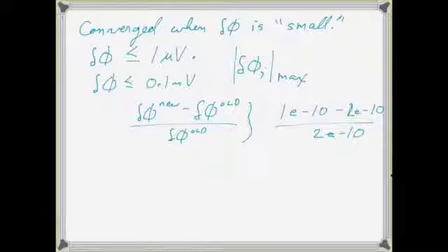You'd find some nodes that just keep going up and down and up and down. Nobody cares. It's something really small, but it's like 100% fluctuation every time, and yet it's 100% of something that's negligible. So when you can, it's much better to look at some absolute convergence criterion.